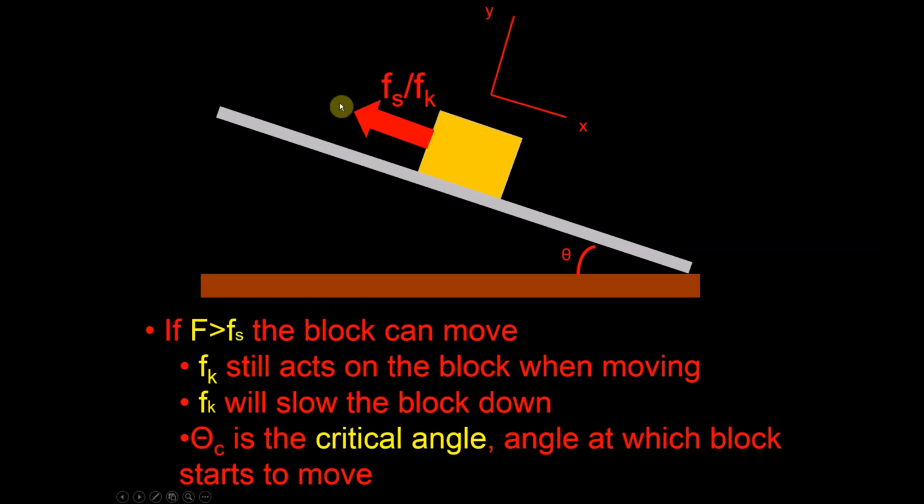Now, remember we're looking for a point here where the force exceeds static friction. Here we have Fs for when the block is standing still, and once the block is moving, it'll be subject to Fk. But the direction of frictional force is still up the slope. This means there will be a force of friction, driving force due to gravity of mg sine theta down the slope. This has an angular component, of course, which means we can keep moving theta here until theta here equals theta c, a critical angle at which the block slips and moves from the Fs regime to Fk.